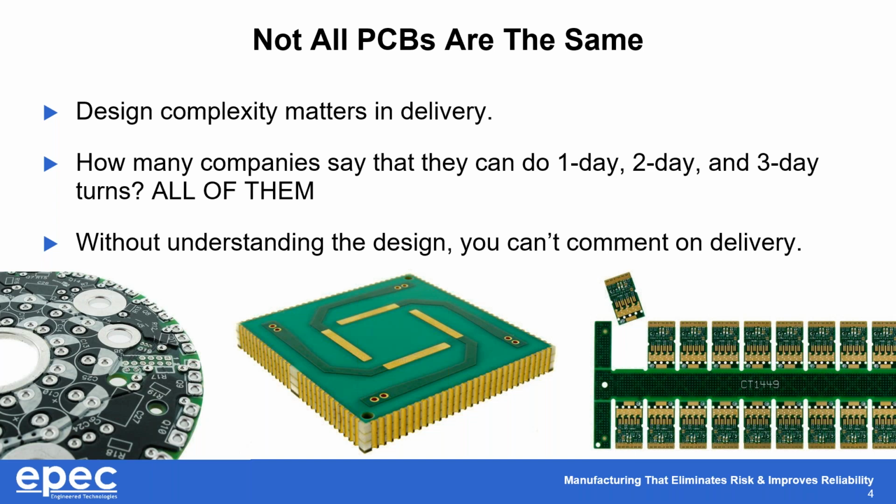And everybody knows that every company says they can do everything. I can do a 1-day, 2-day, and 3-day turn, no problem. 5-day, sure. 10-day, no problem. But the reality is that without understanding the design, you really can't comment on delivery, right? I mean, if you're looking at the part there to the left where it's got selectively plated up 5 ounces of copper, there's no possible physical way that can be done in 5 days.